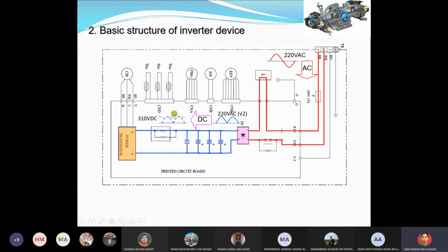Again, in the video they also mention that once the switching is on, it will store the energy inside the capacitor. But once it becomes empty here, it will discharge, so that we maintain the energy. In this case, the bigger our capacitor size, the smoother our signal actually is. So we assume that just after the DC bus, the DC voltage is quite a straight line.